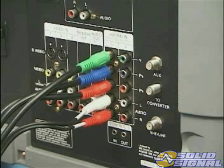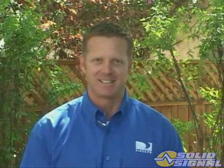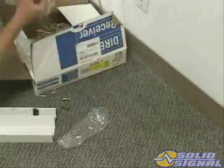Connecting the H20 receiver to the customer's equipment is the same as the H10, so make sure you make the best connections possible. Check the test channels on all receivers to ensure the signal strength and picture quality is excellent from all satellites. As always, activate the system, educate the customer, and clean up your mess.